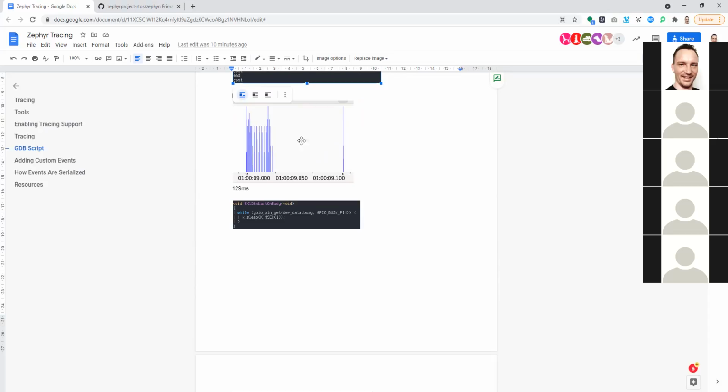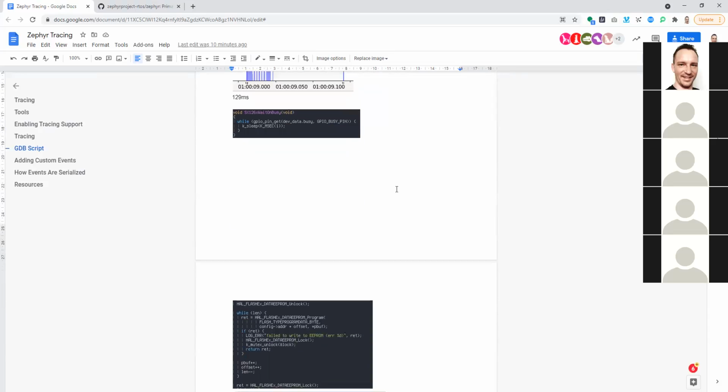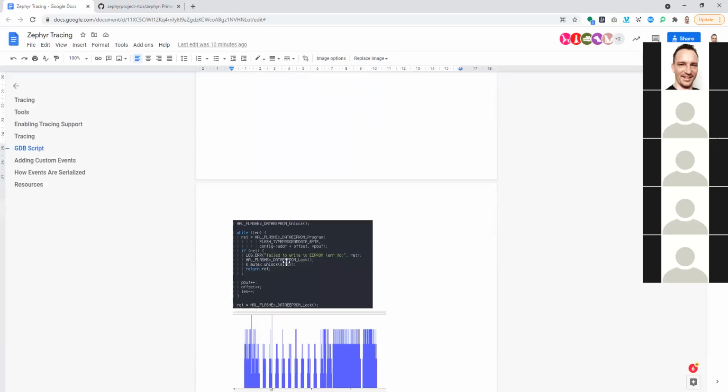So we can look at, maybe we can put this call to save things in the internal EEPROM somewhere else, or maybe we can do it less frequently, so that we can put the chip to sleep and not have to consume power during this time here.